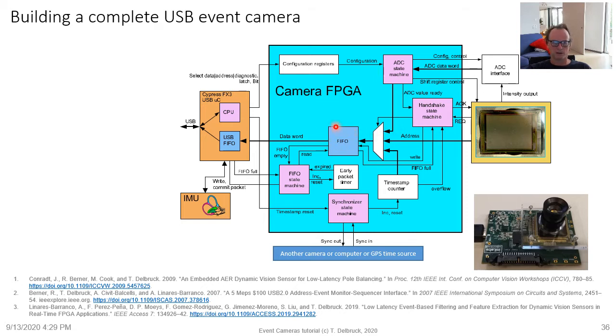But anyway, there's another set of FIFOs here that again buffer the information slightly, because the data rate is variable, you want to minimize the chance that data is lost. Now you can always lose data because if the computer gets too busy to service the data, these FIFOs can overflow. So you have to have a policy for what you're going to do when the FIFOs overflow. Usually what we do is we discard the oldest data. We always make sure that we send the latest data.